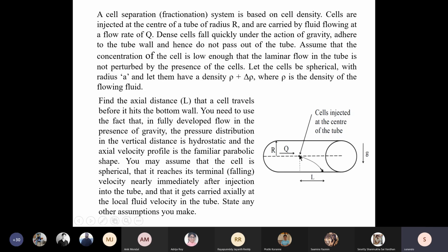Let's say once the flow has become fully developed, so that's the tube. The flow takes place through the tube, and it would require some length, as you all know, the entrance length, let's call it L entrance, for it to become fully developed. So the profile is simply going to be like a parabola from that point onwards.